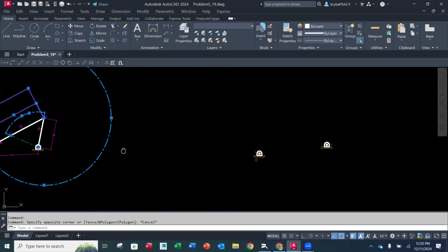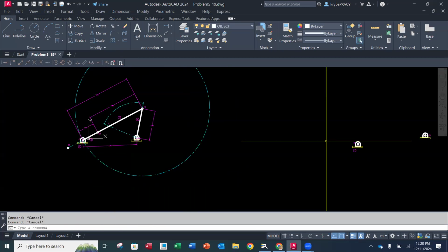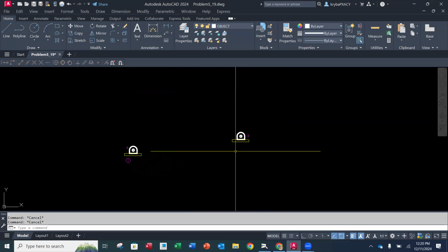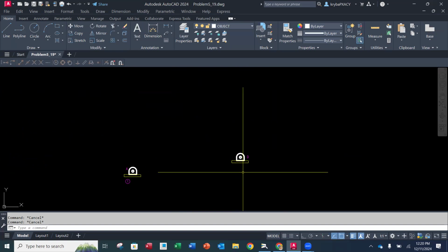So basically, I have kind of the finished version over here, but I'm going to go through the process with you guys so you know exactly what we're going to do. I'm going to pick that same 4-inch length. This is where you as a designer get the discretion. They're not giving you in the problem what the length of link number 4 is. Okay, we get to pick this. Just like remember in the last problem when we had the offset slider crank, we got to pick theta M. All right, we just have to give it a number. So that's what we're going to do here.